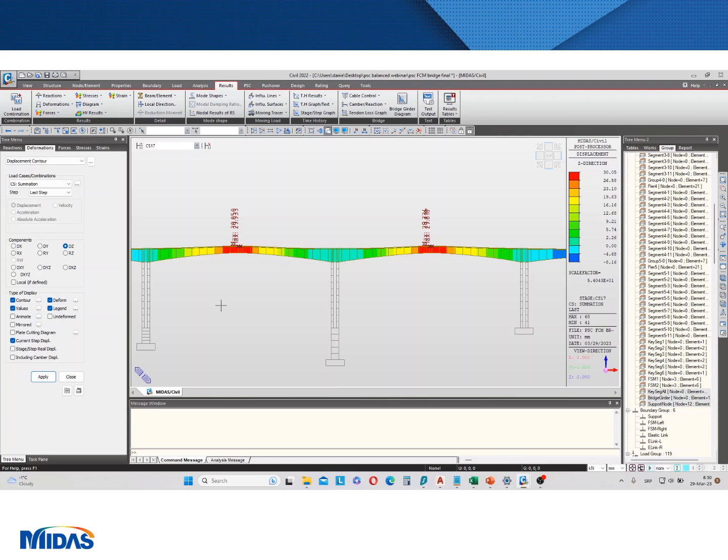And usually we want our top surface of superstructure to be straight, to be flat. So this would be considered as designed elevation, and necessary overheight would be a pre-camber, which we get by setting the formwork actually to the correct position.